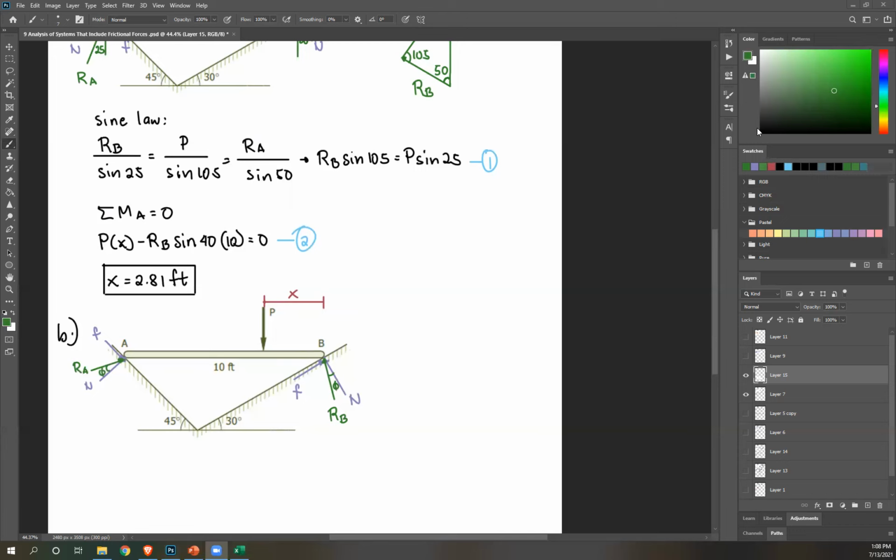Again, we're going to use your triangles. Once again, we can start anywhere. Let's try starting with RB. So this is your RB. Next, RA. And then don't forget, closing your triangle, P is downward. We'll just make this bigger. So this is RB, RA, and then P. And like what we did earlier, let's figure out our angles.